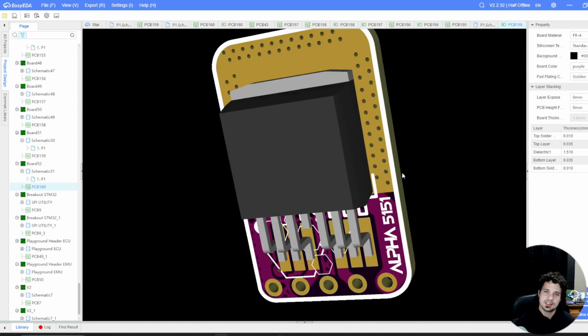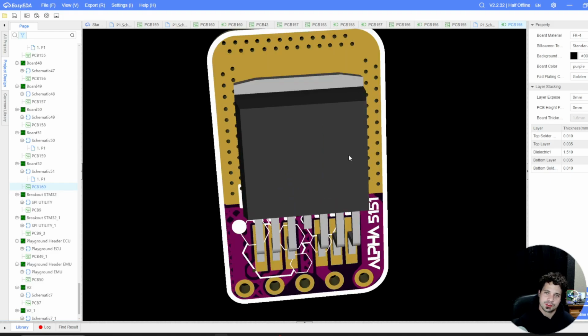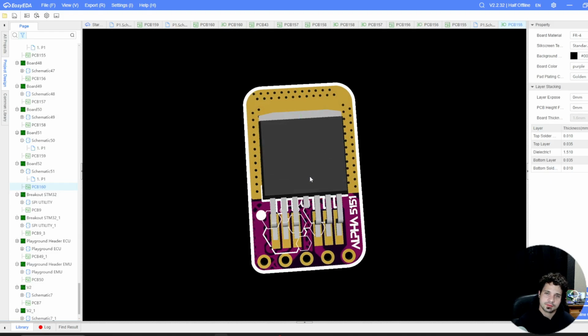So when VTEC is actually commanded in the car, there's a few different things that happen. There is a 12 volt signal that sits on one side of the high side switch that we're looking at here, okay? So just picture this in your head real quick. One side of this is an input and it has 12 volts going to it all the time. The other side is an output, okay? And the output side will have 12 volts come onto it when it's commanded by the ECU. That 12 volts on the output goes to your VTEC solenoid.